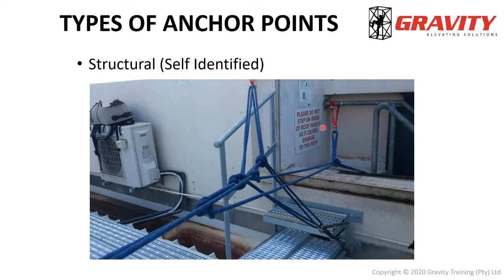So the issue with self-identified anchor points is it relies heavily on the technician's competency and experience to know what's safe and what's not safe. And that's why it's so important to have the correct training, as well as to have competent supervisors on site when dealing with sites and situations where you have to use self-identified anchor points.